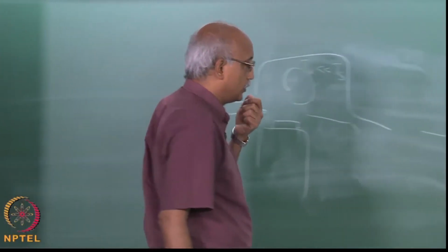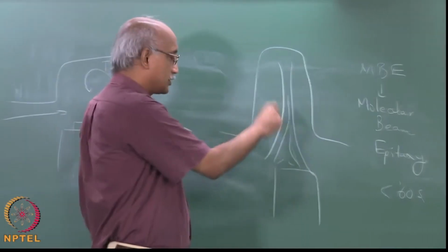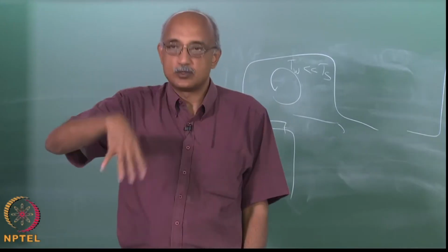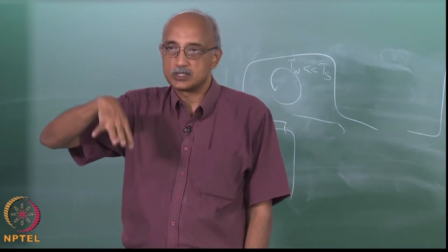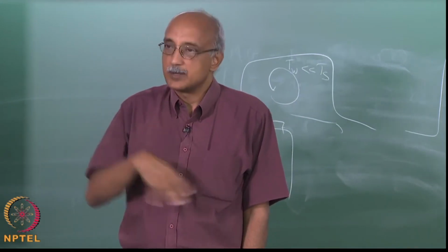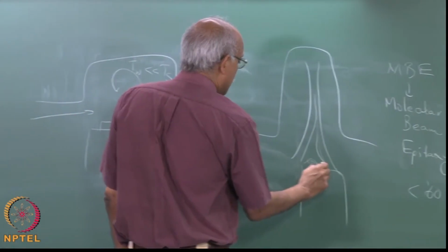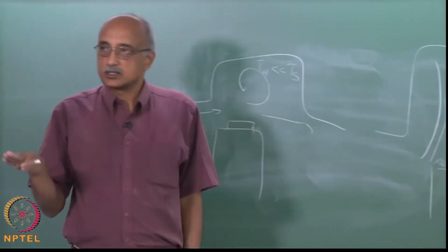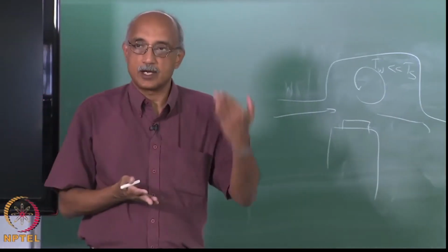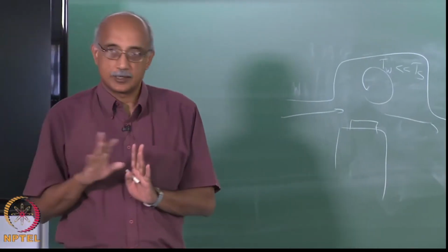A lot of those problems can be overcome by using a stagnation point flow reactor, because here the flow is predominantly directed towards the surface. So, even if your wall temperatures are much lower than your substrate temperatures, the downward flow of the reactant gases is sufficient to prevent significant recirculation cells forming and taking the material away from the substrate. Of course, in stagnation point flow you can also have localized recirculation cells, but they are contained to a region very adjacent to the substrate. So, the effect of these convection rolls is not felt through the entire reactor. They are localized, and their influence can therefore be kept to a minimum.